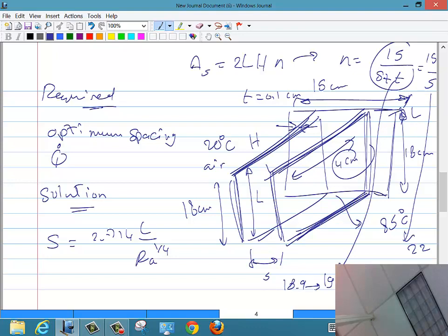All right? So having said that, in the exam, I expect you to go with 18. Of course. But in practice, even if it's 18.9? I expect you to say, well, let's go for 18, but you can write the comment that I would actually risk having my Nusselt number drop, because it will drop in this last fin or the last pair when you squeeze them. You would say, I would risk losing my Nusselt number a little bit in the last part to get one more fin. That's a bigger area, right?